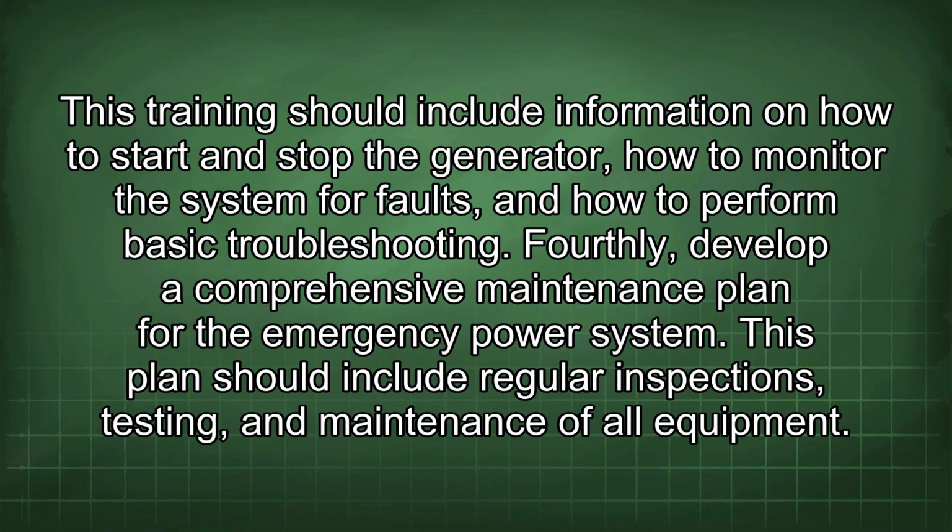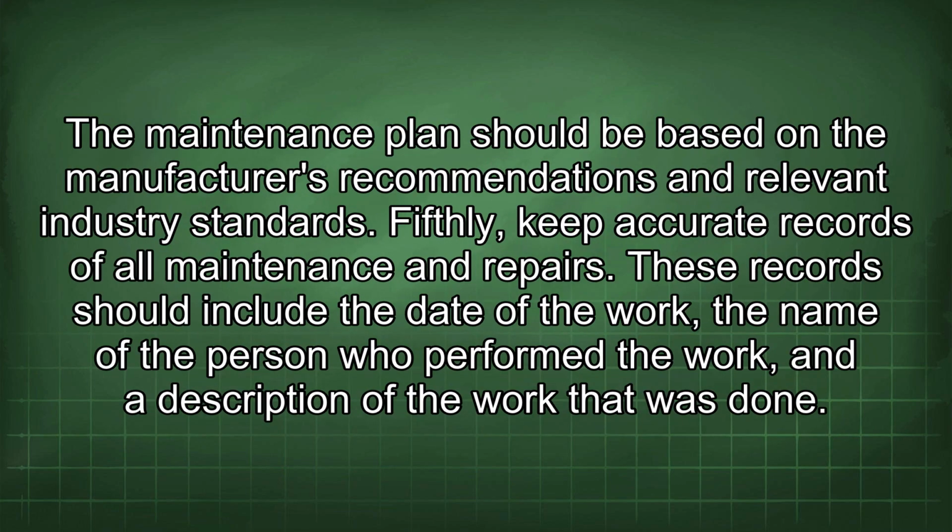Fourthly, develop a comprehensive maintenance plan for the emergency power system. This plan should include regular inspections, testing, and maintenance of all equipment. The maintenance plan should be based on the manufacturer's recommendations and relevant industry standards.